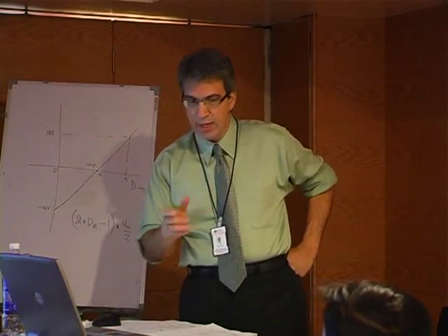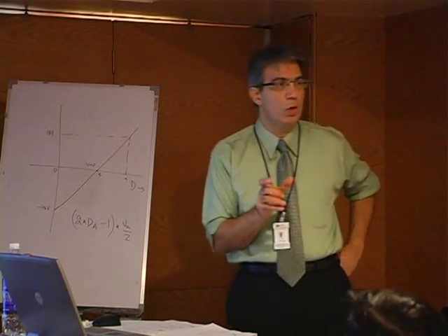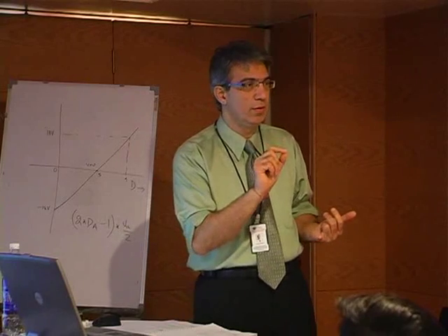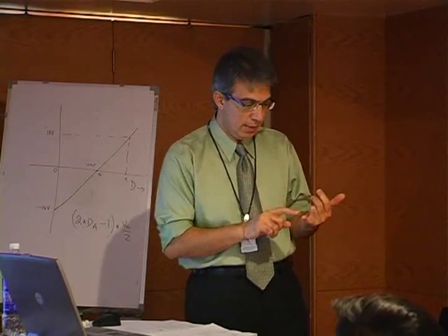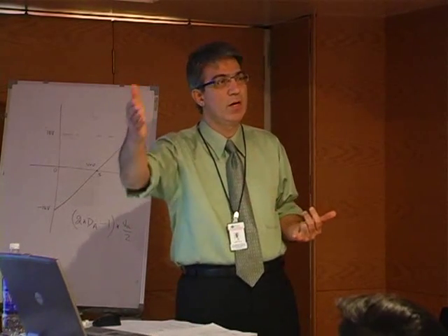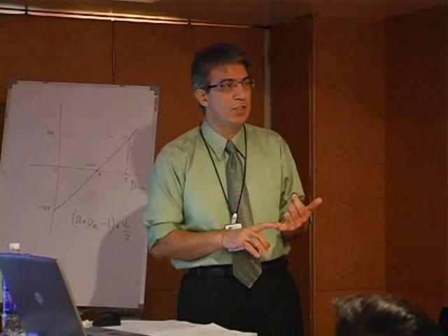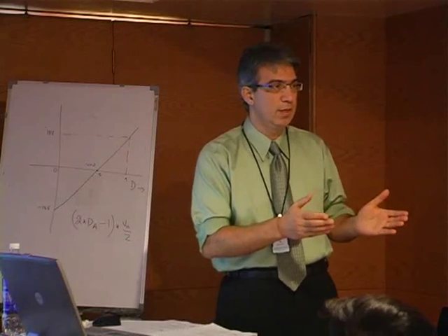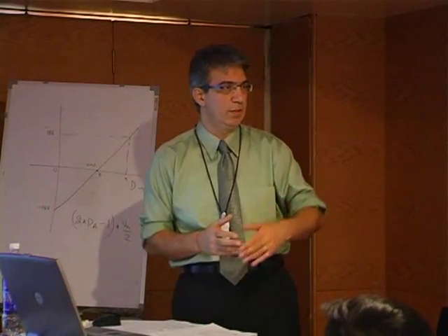Your question is, yeah, I think when you have a variable frequency, you can't do a whole lot except make sure that, number one, MF is an odd integer. That's number one. And number two is that MF is large enough. If MF is large enough, let's say your frequency range is up to 50 hertz, let's say you go from 10 hertz to 50 hertz.